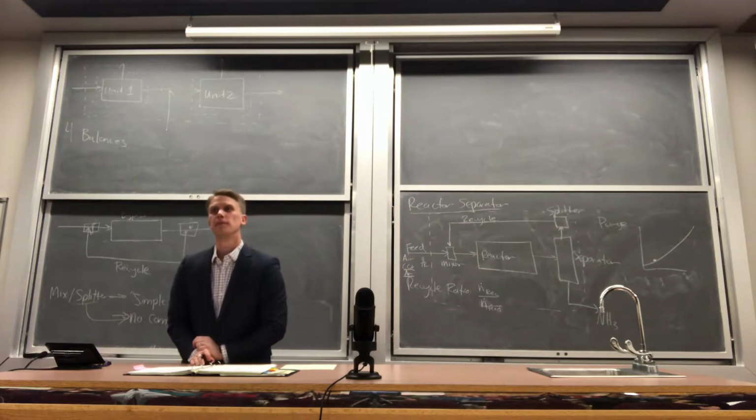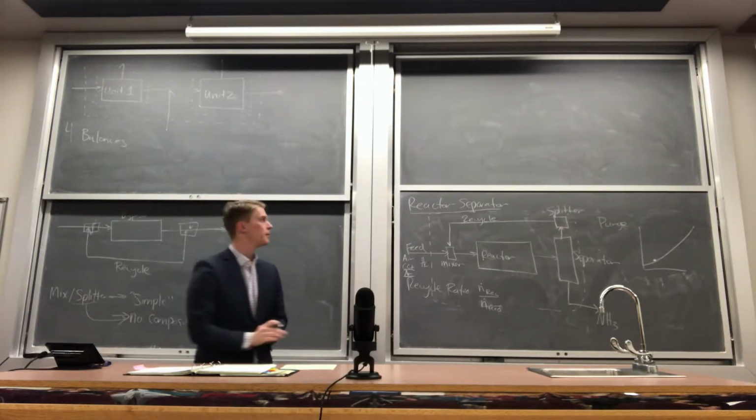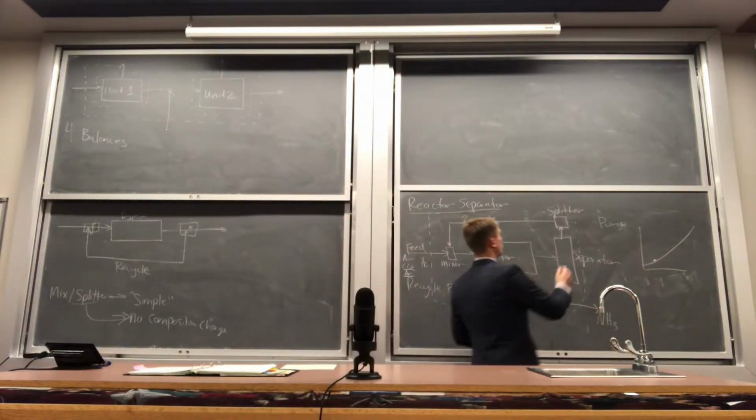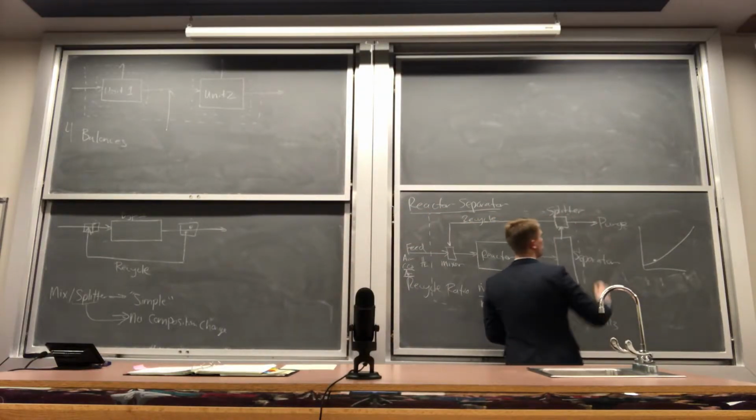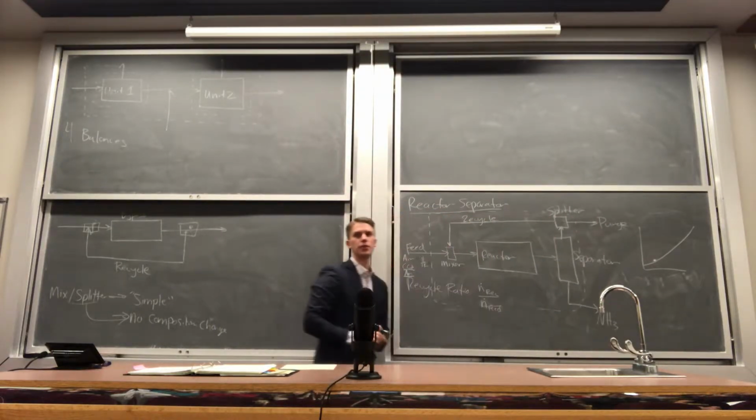Yes? So like in the separator, as you keep changing the temperature, you get it to a temperature that separates the argon and then open the purge stream? Or what is this? No, the purge stream is continuously flowing. You just have to throw some material away to prevent accumulation.